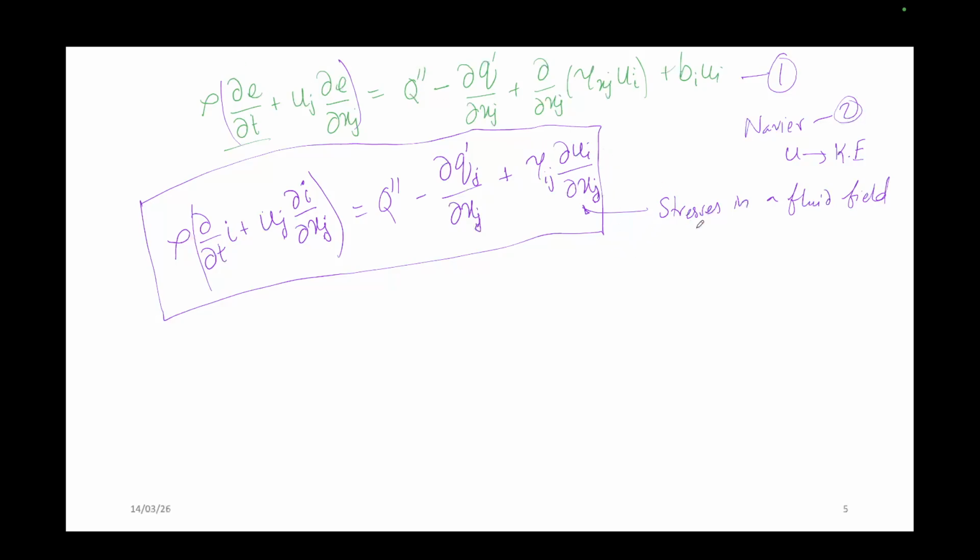So this is your viscous dissipation. Because of the viscosity in a fluid, whatever heat is generated there is converted into this equation. So all these terms are important. These three terms: one is the heat generation in a specific volume, next is the surface heat flux, and third is because of the viscosity. So three terms basically are there. Please remember this. We have considered three terms, right?